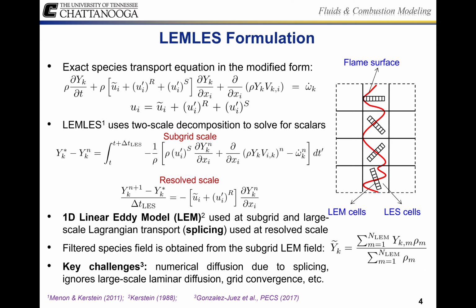These limitations are very well known and are of pretty good concern, as they do not asymptotically achieve laminar or even the DNS limits as originally implemented, only as a true LES SGS closure. The effective heat release is also included within the SGS model by carrying out an explicit expansion of the 1D domain, ensuring proper mass conservation.